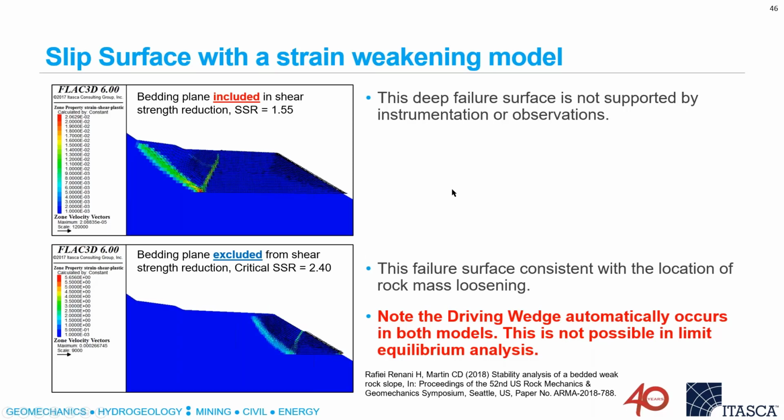So two points relate to this. One is that very often internal deformation is important, and this could either be rock mass or we could have inclined structures which are dipping at what I will call a toppling orientation, but maybe they're few and far between, so we don't see toppling, but we can see internal deformation.